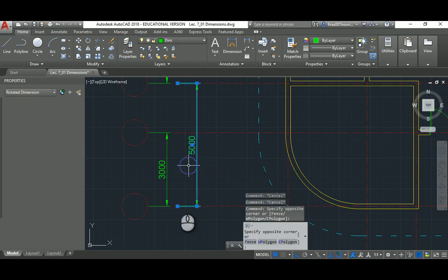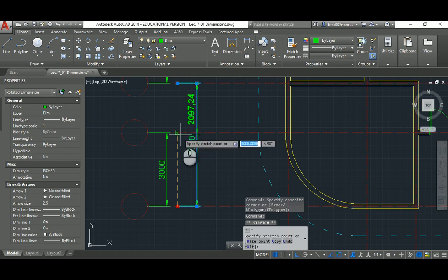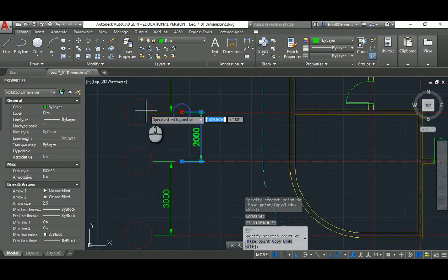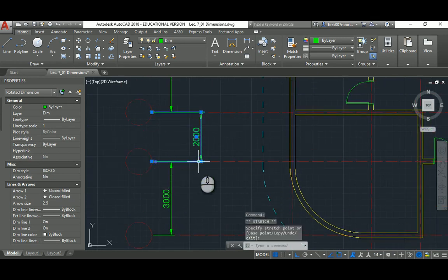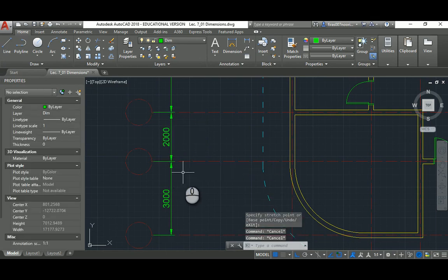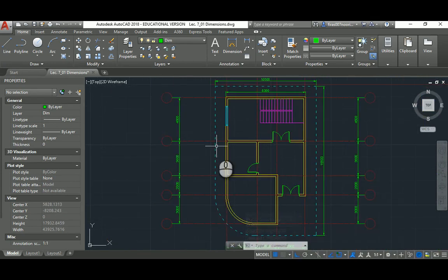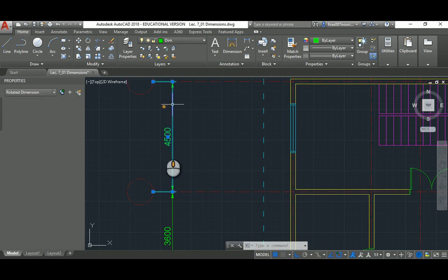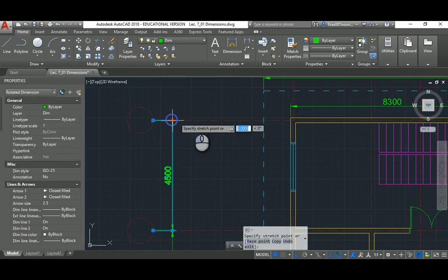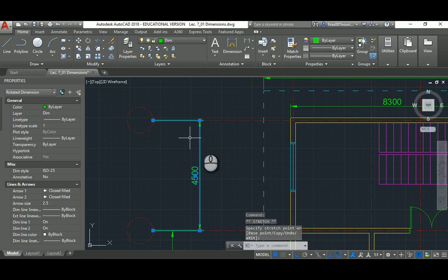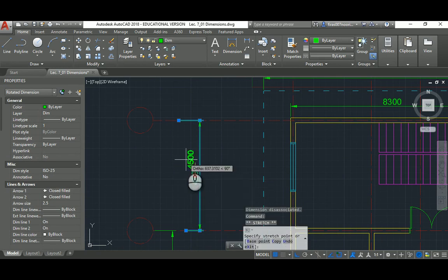I know you can fix it that way, by dragging this, or probably dragging that too, but it might be really long, unnecessary extra steps to fix this. So that's almost it about dimension linear and dimension continuous. Again, as I said, you can select it and drag it to move it later on. Drag one leg, it's okay. Drag two legs, it's also okay. And you can even manipulate the location of the text.